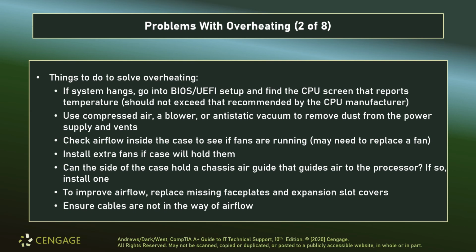Make sure that your faceplates are clipped in place correctly, that you don't have things just sitting open. That makes it very difficult to get enough back pressure with your fans to force the airflow necessary to get a very high rate of air movement, cool everything down efficiently. Also make sure that there's not cables in the way. You don't want things just kind of hanging that could block the fan and cause it to lock or stop. You also don't want a cable to accidentally become damaged by impact with another object.